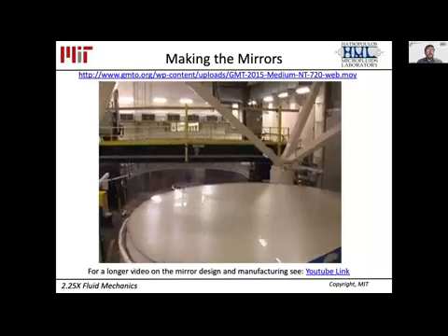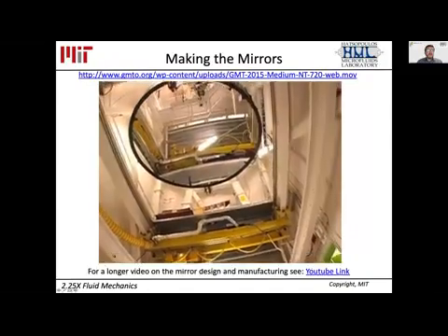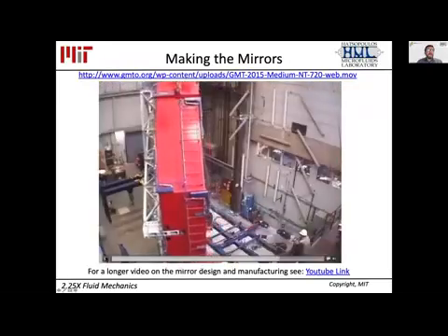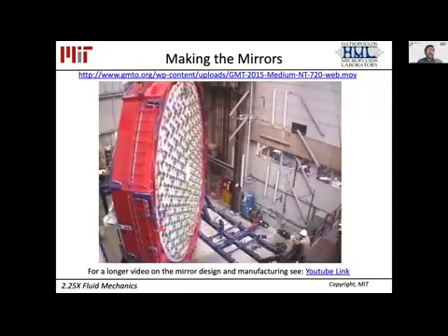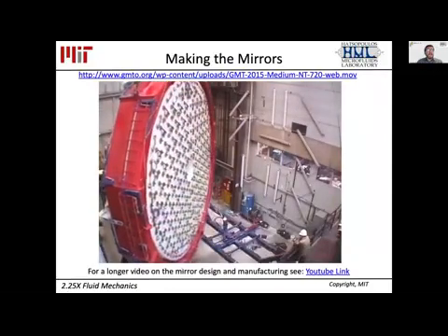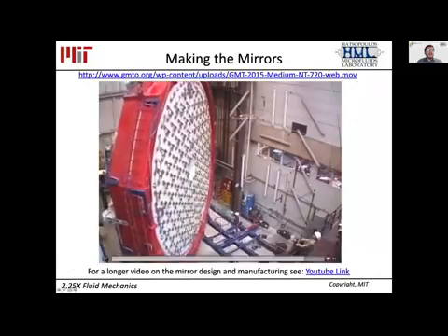And finally, here is the final mirror, and here's an example of what it looks like having been hoisted up and coated. This gives you a good view of the backside of the mirror, and you can see that on the hexagonal pieces there are individual actuators that are shown here, and these are to locally adjust the focal length of the mirror to correct for aberrations in the atmosphere. So this is what's called an adaptive optic. But on the other side of this, it's almost a perfect parabola that's been produced by this idea of just rigid body rotation of a liquid to produce a parabolic surface.